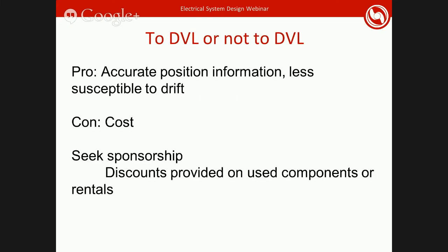Okay. The next one is what I call 2DVL or not to DVL. As you've probably heard, DVLs are a great asset to have on the team, as they allow you to have pretty accurate positioning in the water, and they let you know if you're starting to drift. Say you can see something with your camera, but as soon as you zoom in and get really close to the object, sometimes you lose vision and start drifting. It's more likely that you will miss your target or have strange complications. Maybe you're following a pipe, trying to find your next task, and relying on your camera to kick in, which is only visible up to a certain range. Sometimes you'll be off your mark, and it will take much longer to find where you are and run your search algorithms. Therefore, having a DVL is a great asset.